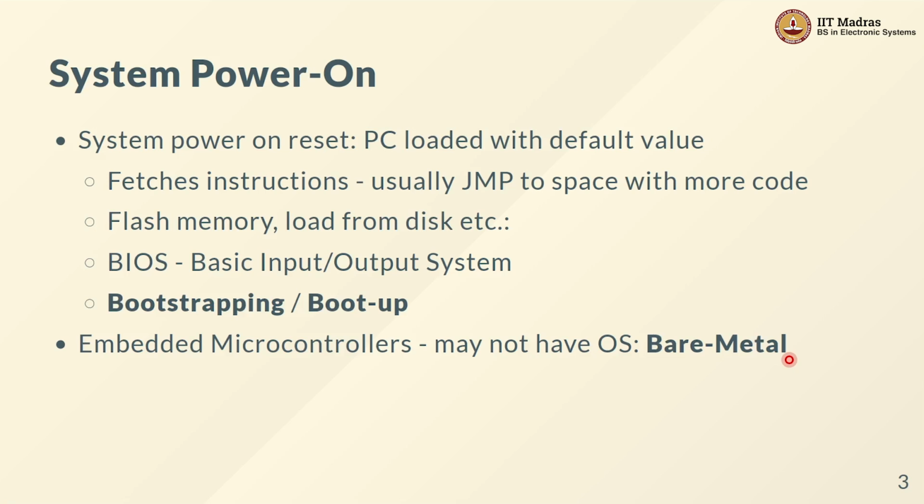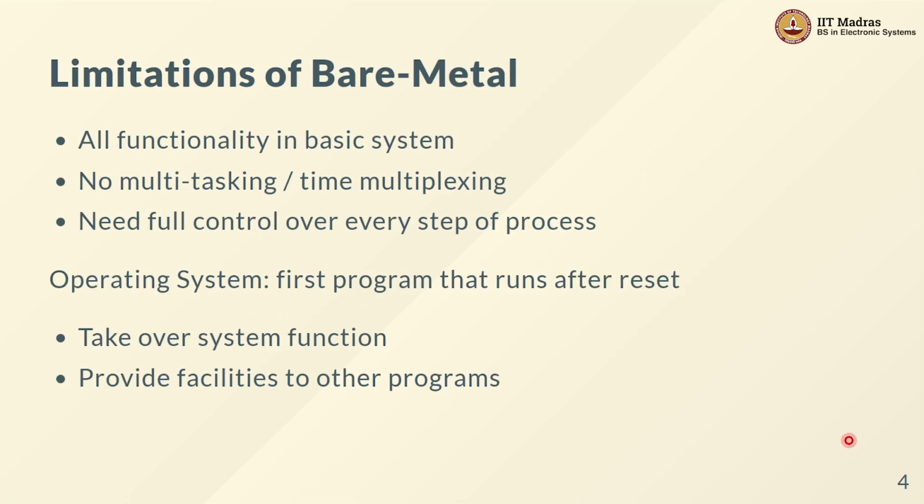Now, you can probably already imagine that this is very limited, right? What happens is all the functionality that you want has to be baked into this basic system. If you wanted to communicate with a serial port, the driver corresponding to a serial port, or all the register functions to talk to the registers in the UART interface need to be declared in your program and compiled in. In general, it does not have a concept of multitasking, or time multiplexing between different tasks. If at all you want to have 2 different things or 3 different things being processed by the same thing, you need to be explicit about it.